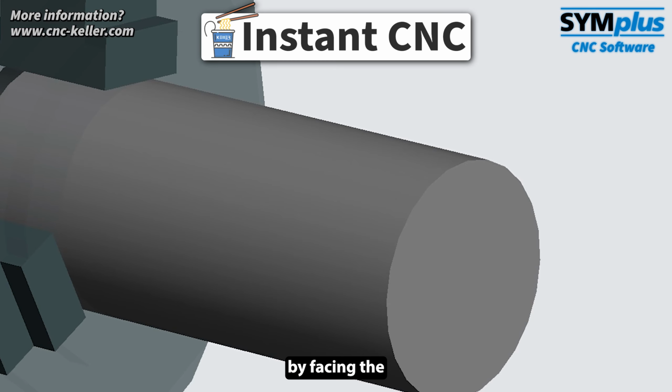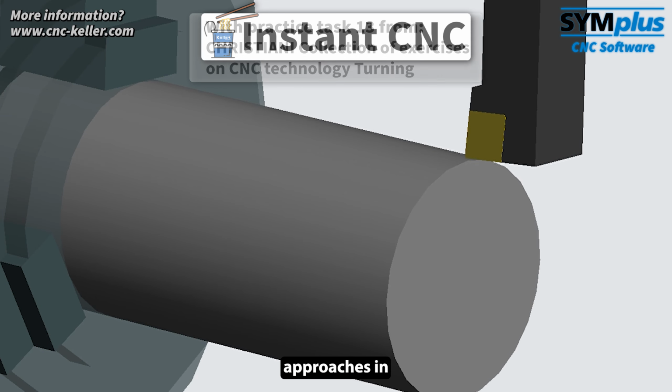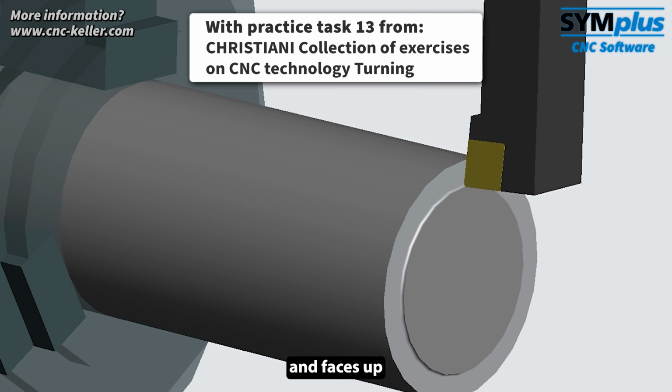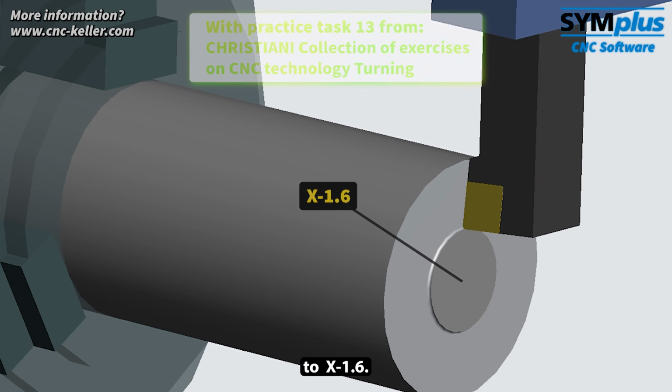We start by facing the front face. The tool approaches in rapid traverse and faces up to X minus 1.6.